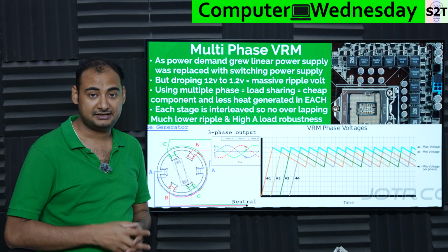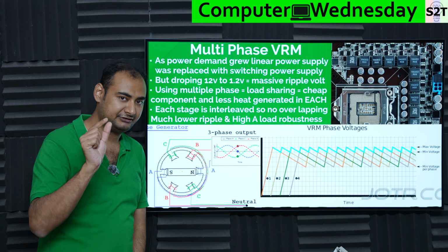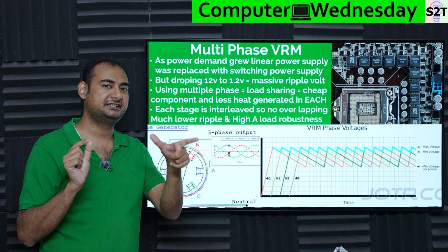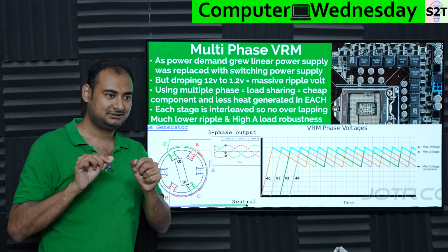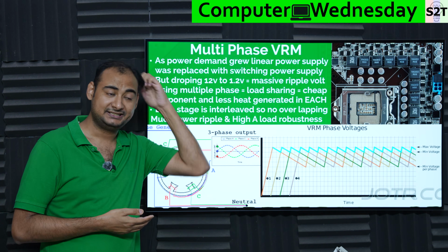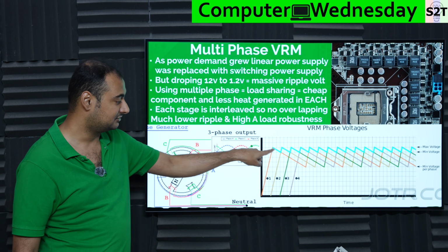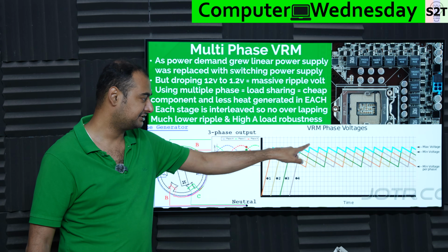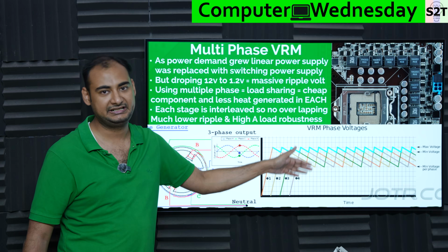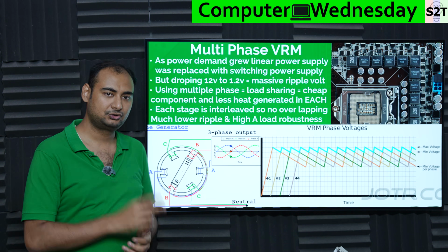So what do we do? And here's the problem. You have to drop from 12 volt to 1.2 volt, meaning off time, especially if you are using a PWM system, there is a lot of dead time. Where it's like you're 12 volt and you turn it off for 90% of the time. And like, how the heck does power go? Yeah, it's draining from a capacitor and inductor. And the problem with that is your voltage is dropping. So you charge it on, dropping, charge it on, dropping. And you're like, wait a minute, that's a very ripply thing. Yeah, idiotically ripply.